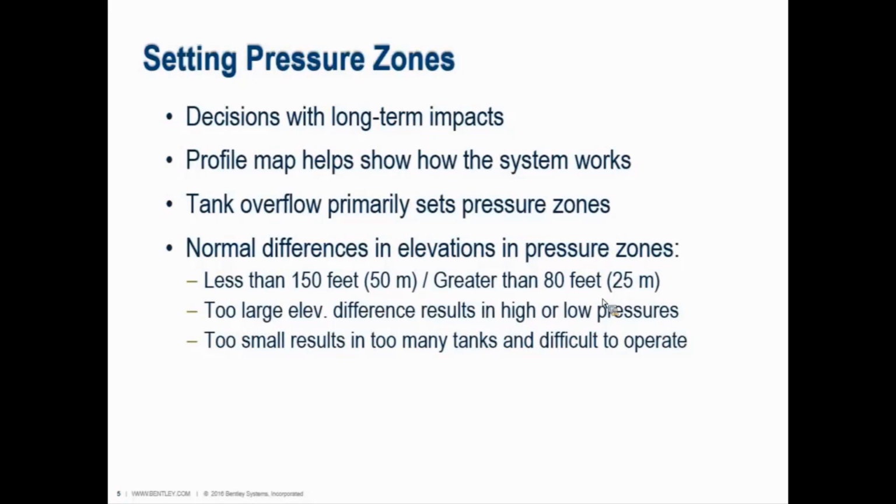And if you have too broad of a range of differences in head elevations, meaning a very broad pressure zone, then you're going to deal with lots of high pressures in some areas and low pressures in other areas, and it's going to be very tough to maintain because you're going to have different problems depending on where you are. You might have to use higher pressure, more durable fittings in some high pressure areas, but all within the same pressure zone.